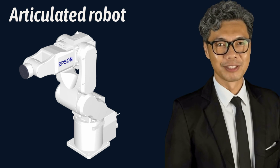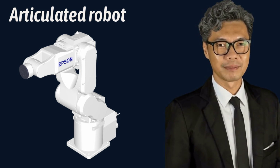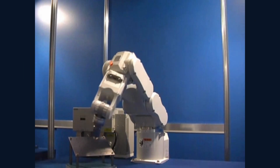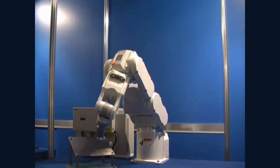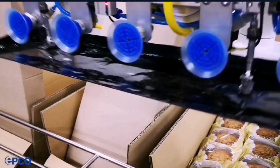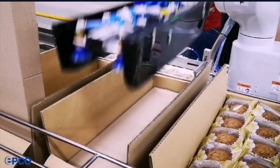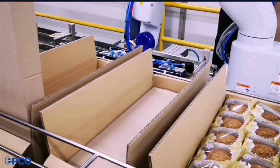The first type is the articulated robot. Most people call it a 6-axis robot. Select an articulated robot when your object is not lying flat or the process requires changing the orientation of the object. If you need to pick a part lying at an angle and present it vertically or rotate it from one plane to another, the articulated robot handles this naturally.